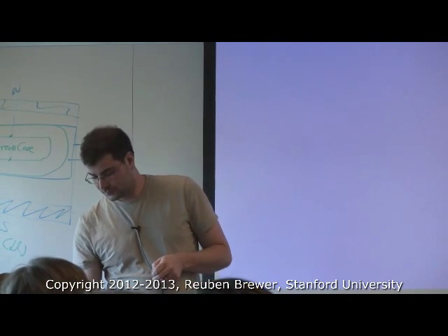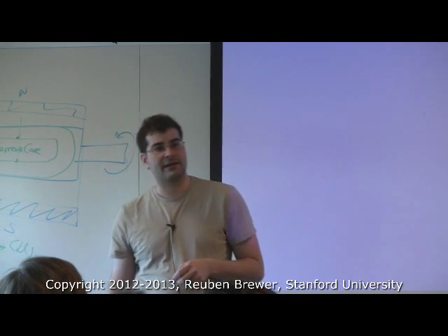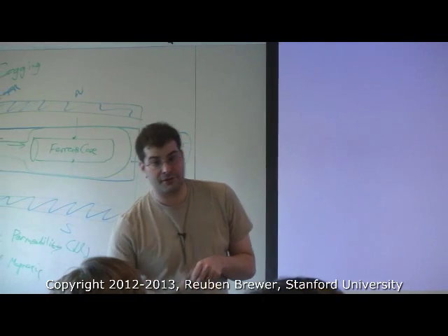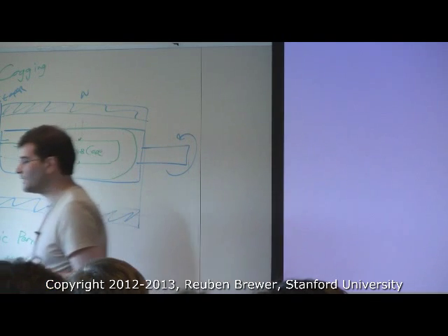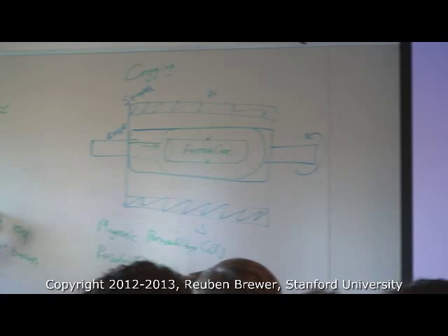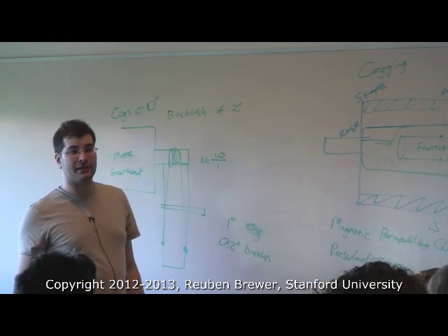Is that what it is? You just uniformly distribute the cogging so that you just have a little extra resistance. Exactly. You have some spatial resolution for feeling cogs, and if you go below that, it doesn't matter, right? Say your spatial resolution is 2 degrees for a cog. If they were at 2 degrees, you could still feel it. All right, so go down to 1, and then you can't feel it. It's still there, but you've mitigated it.